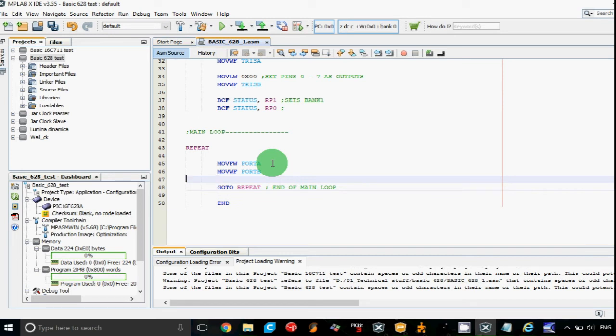Okay, so it's gonna repeat this loop very fast, and every time it sees one of these buttons from the input being pressed, being logical 1, it will turn on one of the first 5 LEDs that we have on port B. By the way, the labeling of the LEDs is from left to right, so it's 0, 1, 2, 3, etc. Okay, so we are only using the first 5 inputs, the first 5 bits, counting from 0, of the port A, because number 5, number 6 and number 7, these pins are already used for something else.